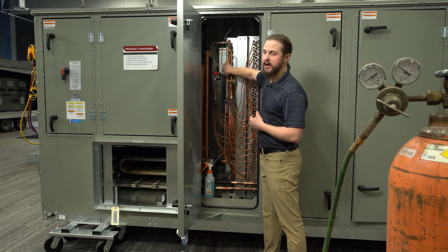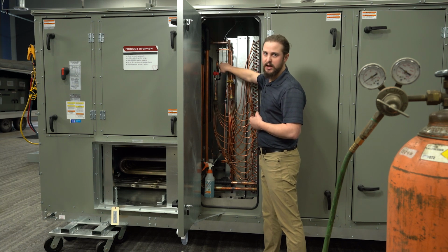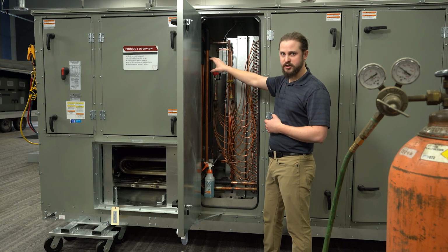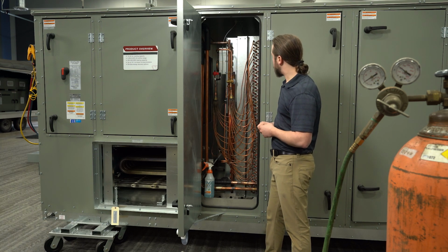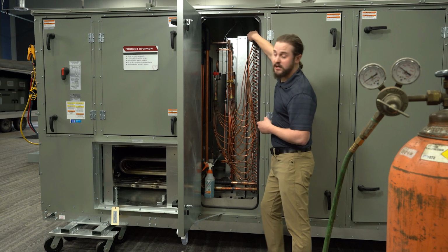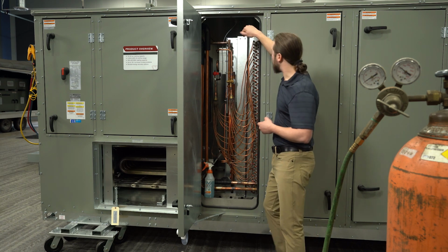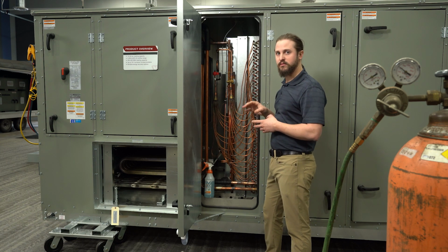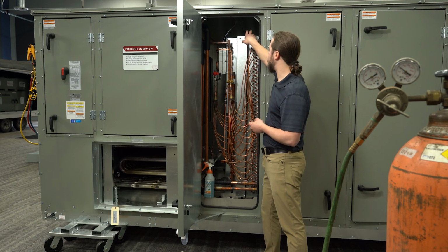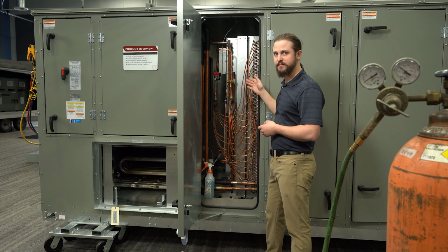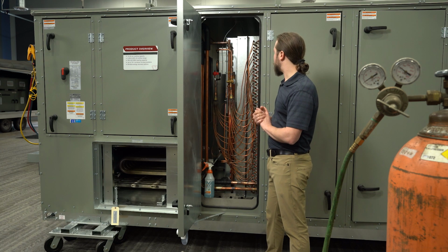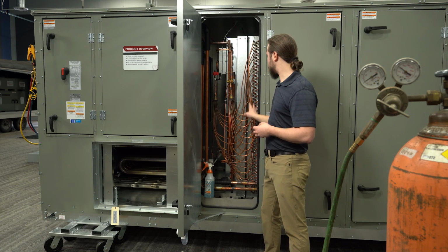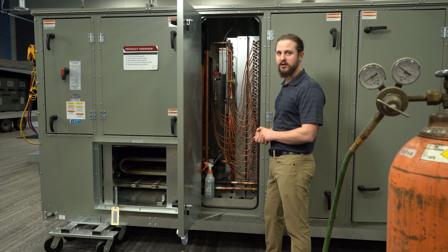Indicated typically on this bracket, you will actually see a label for circuit A and circuit B, and that's the same circuit that'll be labeled in your compressor section where we were earlier. Now, say we have a leak on this top circuit B, and we're going to have a torch in here brazing. There is a potential that your torch heat could loosen another braze joint on an adjacent circuit. We don't want that to happen. So I would say always remove refrigerant out of both circuits if you're going to be brazing on this section, primarily for the matter of safety.